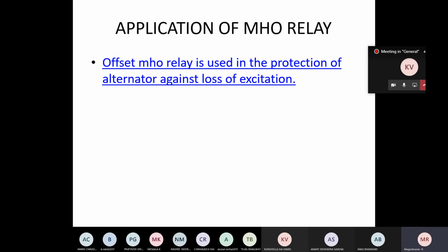It produces the real power with the help of the mechanical input. How does it produce the reactive power? By the field excitation provided to it, a DC supply provided to produce a magnetic field. The magnetic field fed to the machine makes the device produce the reactive power. Once the reactive power is produced by the alternator, the terminal voltage will be the rated voltage.